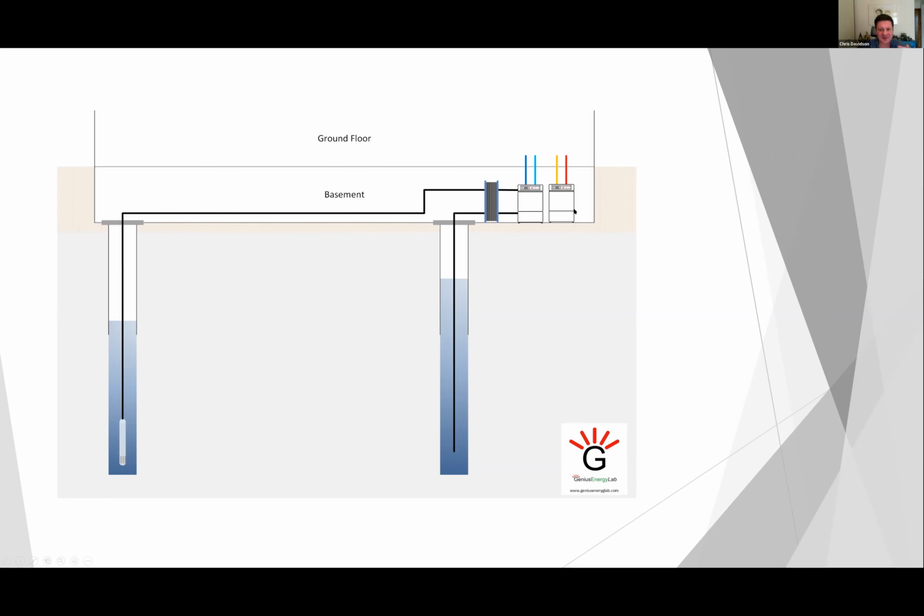Just to go into a little bit of detail on how these wells function, and this is really just lining things up for much more detail later on in the series, but you'll see that the water level here in the abstraction well is lower than the water level here in the recharge well. That's because this pump is drawing that water level down. It's called drawdown, and it's down from the standing water level in the ground. That pressure effectively drives water into the well.